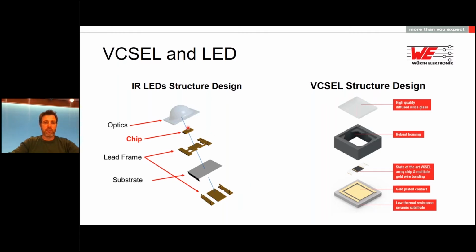Then, of course, the difference is either the infrared chip, or in our package we use a state-of-the-art VCSEL array chip with multiple gold bonding and multiple single VCSELs on it for our higher output. Of course, the housing is specific for every component.